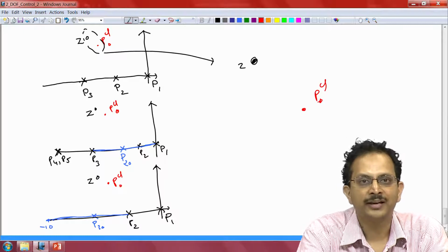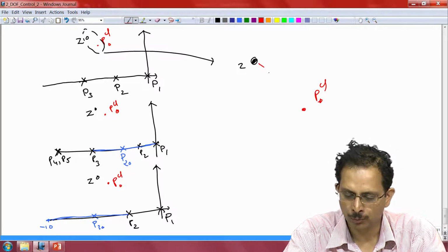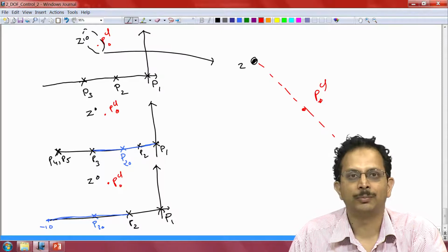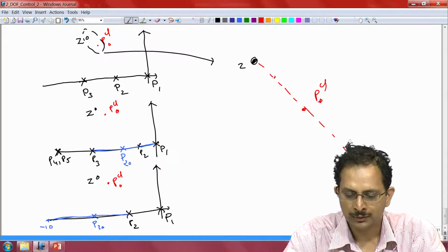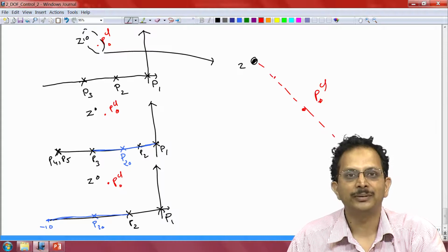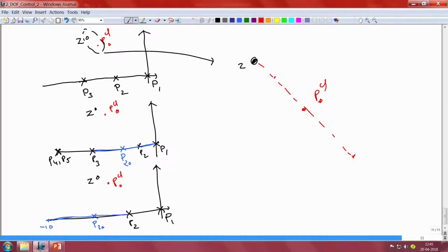Now we know that when the gain of the plant changes, the closed loop pole varies along this particular straight line between the points PCL max and PCL min, which are 1/3 of the distance from the point Z to the point PCL naught and 3 times the distance of the point Z to the point PCL naught respectively. So, this is the line along which the closed loop pole varies if you have uncertainty only in the gain of the plant and no uncertainty whatsoever in either of the pole positions.